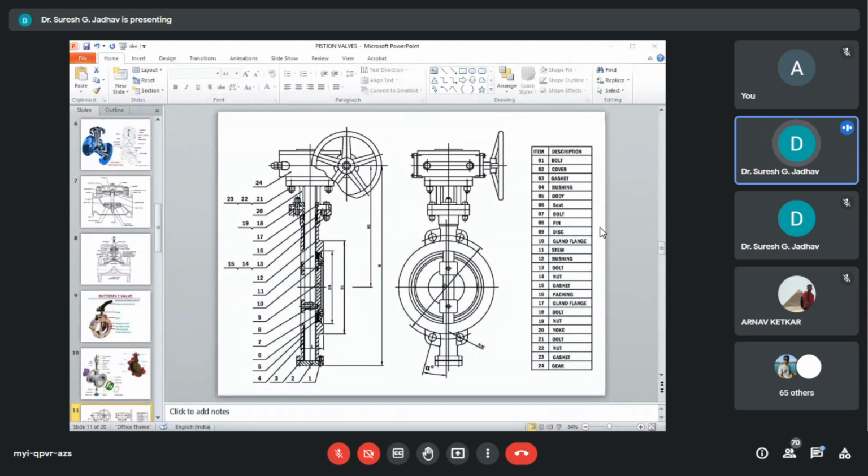Valves up to 12-inch nominal bore size are operated by lever. This lever can have notches to control the flow. Higher diameter valves are provided with gear units and are used as control valves. It can be provided with an actuator. The use of the above valve for high temperature is by the choice of materials.